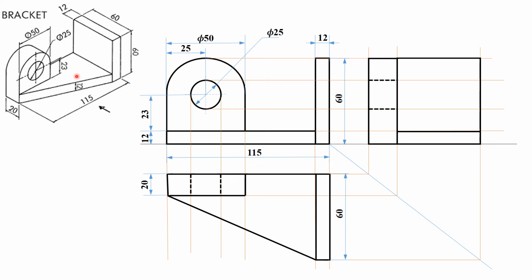But one point I have to look at here is this particular edge. This edge runs from this point to this point. Is that right? Till the point where it reaches here, it will be aligned with this edge, till the moment it falls behind this curved surface. Here you can see this edge as a hidden region along this length, which I have given here. This completes your left side view.